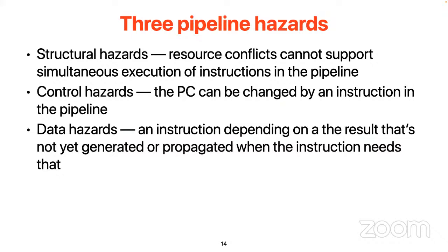Structural hazard means that you have 2 instructions that want to execute simultaneously on the same hardware. Remember, although we allow multiple instructions to perform operations in parallel in a processor, the constraint is that you can only have 1 instruction at a particular functional unit.